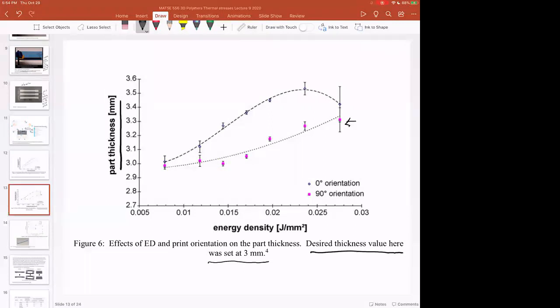And so you have a desired CAD model, you print it on a certain printer, you scan that real printed model, and then compare that three-dimensional real object that now you have a digital scan of to your CAD plans, and then the computer can start to figure out where the dimensions of the CAD model need to be tweaked in order to get the desired part tolerances.